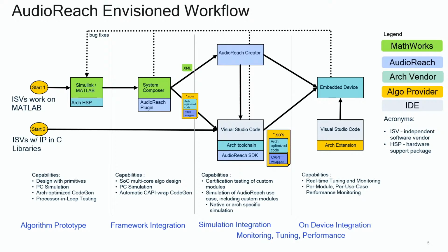when the developer is done with all their validation, simulation, and optimizations in the MATLAB environment and System Composer environment, there will be a capability to export the net list, the use case net list, from System Composer, along with the metadata describing the API of the algorithm modules.